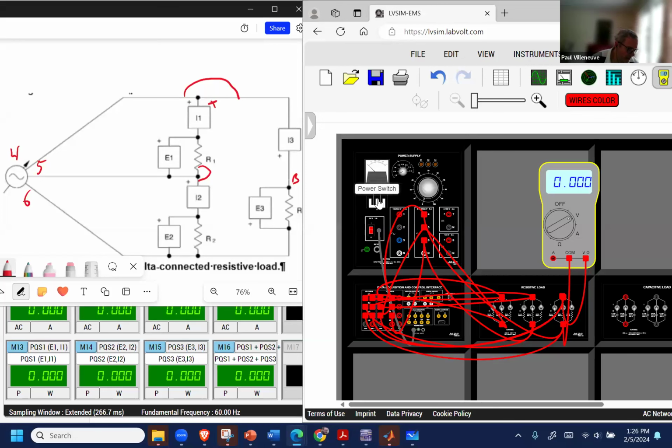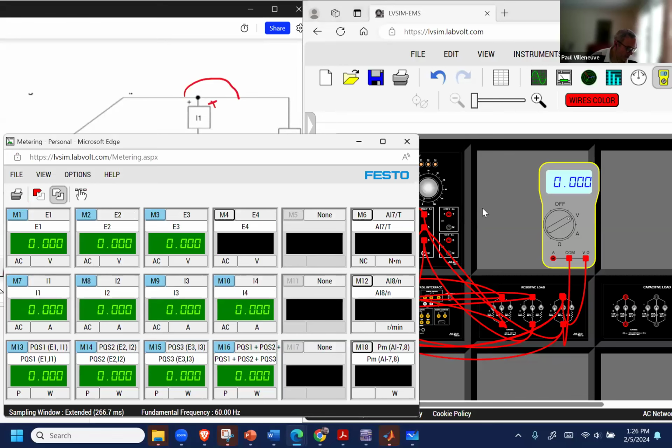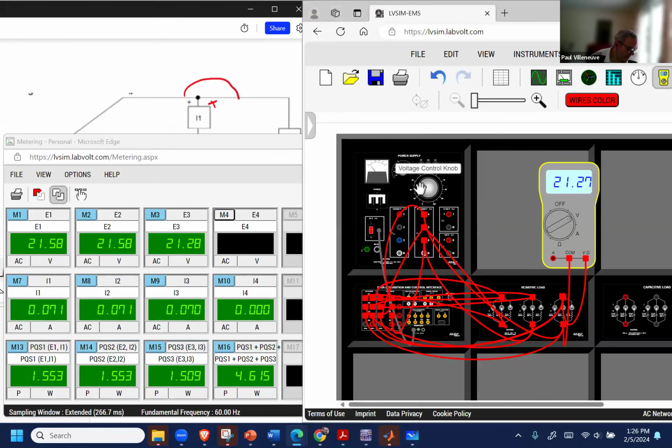So now I'm going to flip the switch. I'm going to look over here, make sure things turn up the way I expect them to. All these currents are about the same. All these voltages are about the same. So I'm feeling pretty good. I haven't exceeded 120, so I can turn this up. So everybody check what I'm doing. I'm going up slowly initially just to see that it's working okay. And then once I get it working okay, I go from there. And as we said, we don't really want to exceed 120 volts. We're a little bit over.